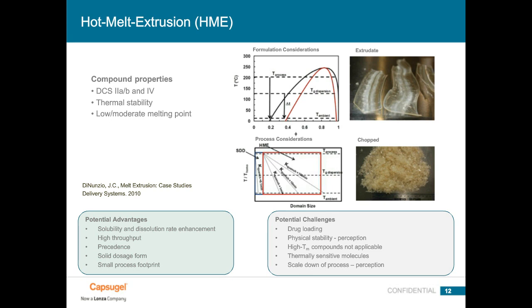Some of the challenges with HME are the narrower space in both compound and excipient properties. Because of the high heat used in HME typically, we have to make sure that the compounds are thermally stable and have a melting point or a dissolution point into the excipients that we use that's appropriate.